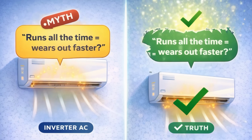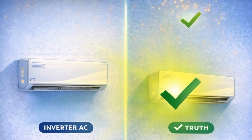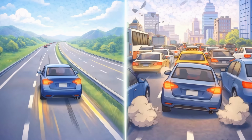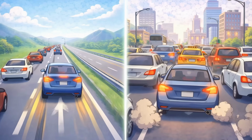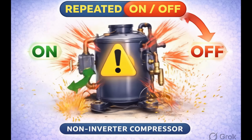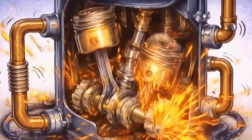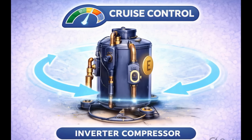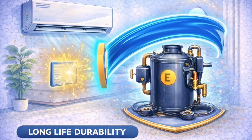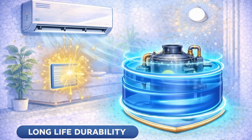There is a common myth that because inverter ACs never stop, they will wear out faster. Actually, the opposite is true. Think about your car. What causes more wear and tear? Driving at a steady 60 miles per hour on a highway, or constantly slamming on the brakes and then flooring the gas in stop-and-go city traffic. The start-stop cycle of a non-inverter is incredibly stressful for the mechanical parts. Every time it starts, the motor jerks, the pistons slam, and the pipes vibrate. An inverter AC, by staying in cruise control, experiences much less mechanical stress. As long as you keep the filters clean and protect the electronics from power surges, an inverter compressor can actually outlast a non-inverter because it lives a much calmer life.